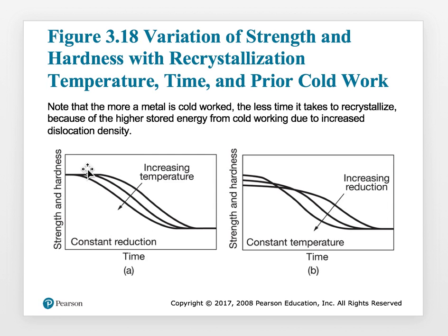So you have to take it to say 3/4 of an inch, heat it up such that the strength actually goes down, and if you can help that, you can actually increase the temperature to say 600 degrees centigrade compared to 400 degrees centigrade. If you heated it to 400 degrees centigrade, you may not decrease the strength to the same extent as if you went up to 600 degrees centigrade.